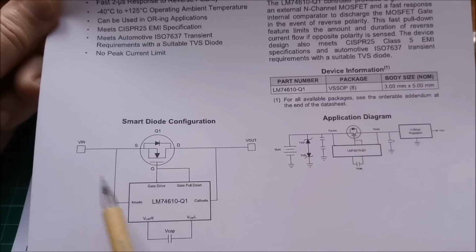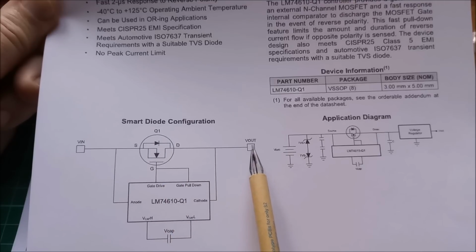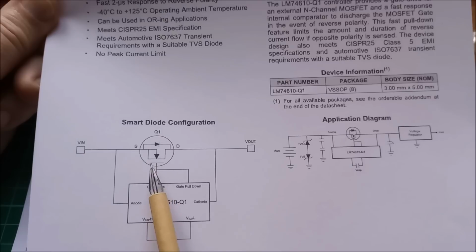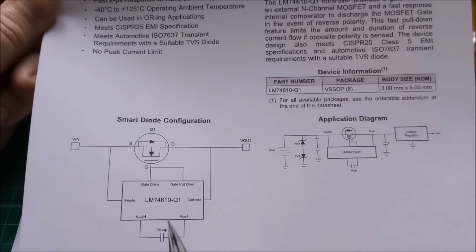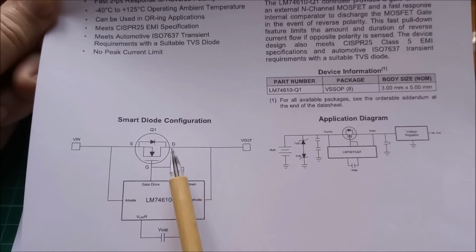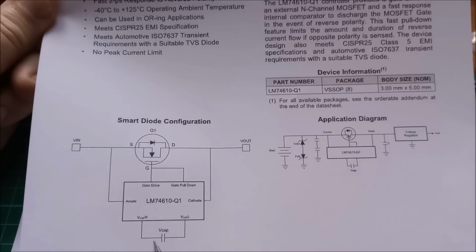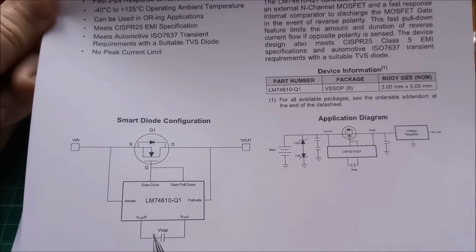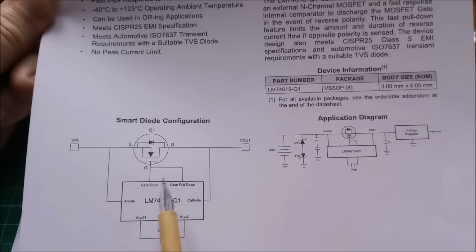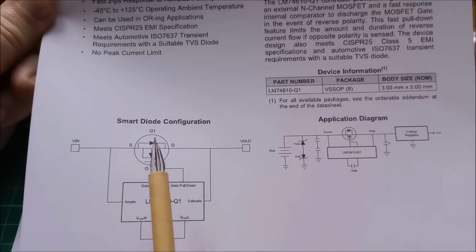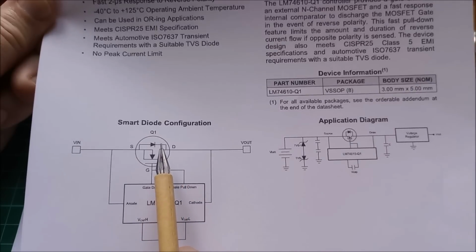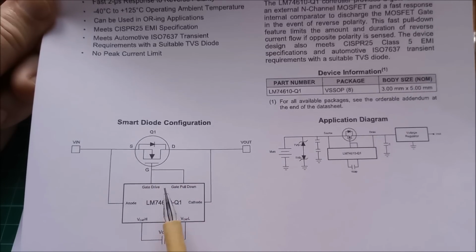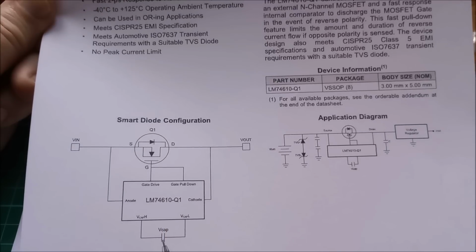And then if this thing goes into reverse bias, so V out goes above V in, the chip detects that and pulls the gate voltage down to turn the MOSFET off. But the issue with this system is that the energy in V cap only lasts for a certain amount of time, then it runs out and the chip shuts down. And then the full current of your system is passed again through just the body diode. That then enables the chip to charge this capacitor back up.